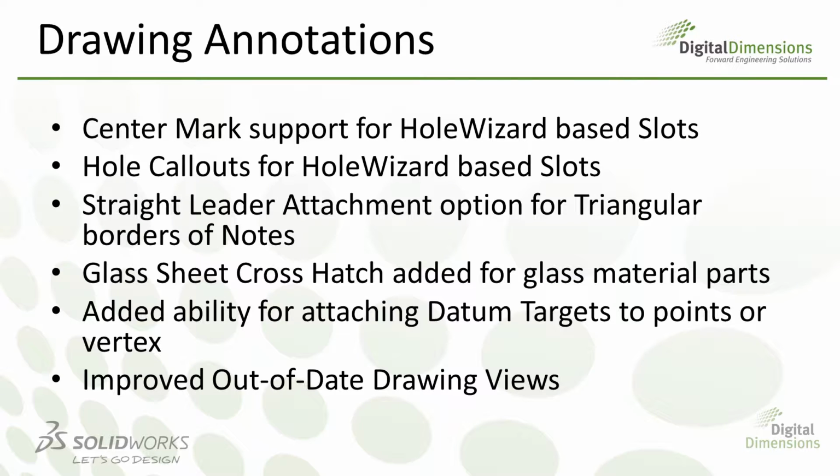Next up for SOLIDWORKS 2014, drawing annotation enhancements include support for Hole Wizard-based slots, which has the two following items. We can now apply a center mark for a Hole Wizard-based slot. This will behave just the same as sketch-based slots always did in the past. But what's really exciting is this next bullet item here, hole callouts for Hole Wizard-based slots. Just like they do on a regular Hole Wizard hole, based on the database, it gives you a nice callout telling you what that hole is. Well, now with the new Hole Wizard-based slots utilizing the same technology, the hole callout will now call out our Hole Wizard-based slots.